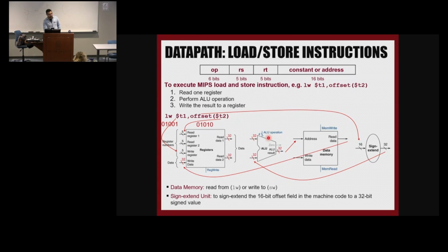So you see these signals here. We have ALU operation, in this case 4 bits, for example. The 4-bit signal selects the kind of operation I want to do. It's add, subtraction, or whatever. Then we have a memory write and memory read, which is similar to the register write. These two should be activated if I want to read something from the memory or write something to the memory. These are also 1-bit signals, either 1 or 0, and they define whether we want to write something to the memory or not, or read something from it or not.